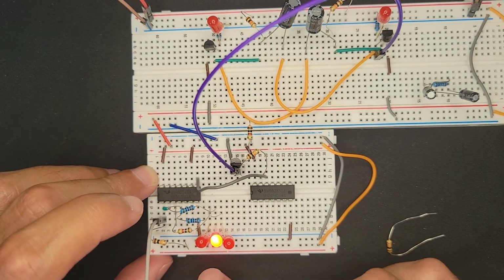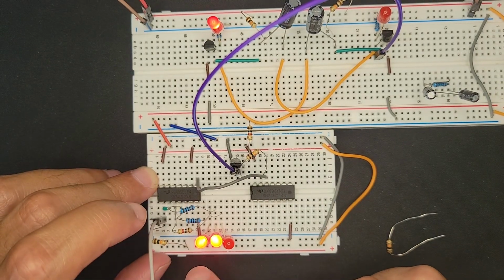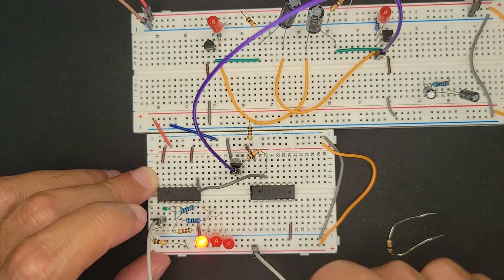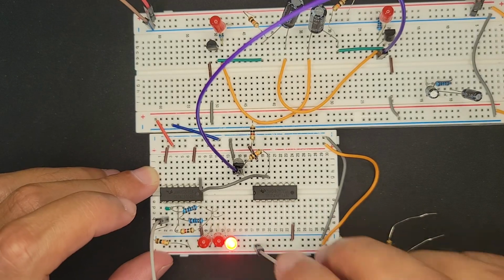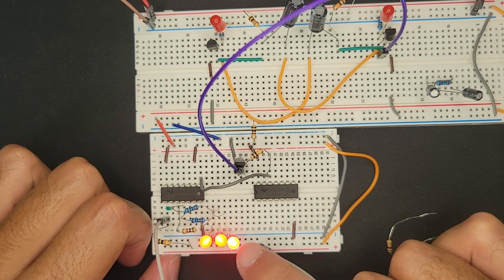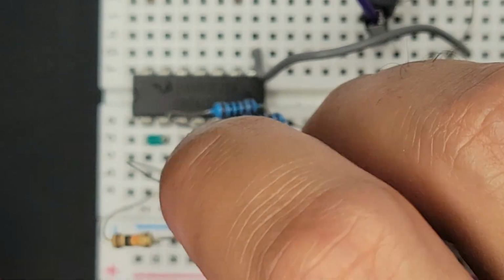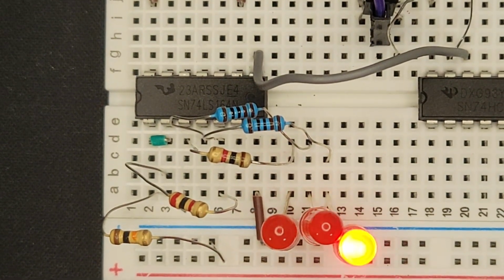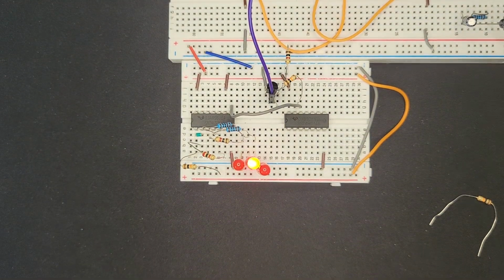So we're just feeding the first bit when I plug this in, and the rest will just shift down. So we should have 0, 1, 1 there, and then 0, 0, 1, and then we'll have 1, 0, 0. Okay, I plugged it in. 0, 1, 0. 0, 0, 1 should be next. Okay, this is perfect. So now what we have to do is put the output of C back into the input of A. All right, so that seemed to work, just connecting them together.